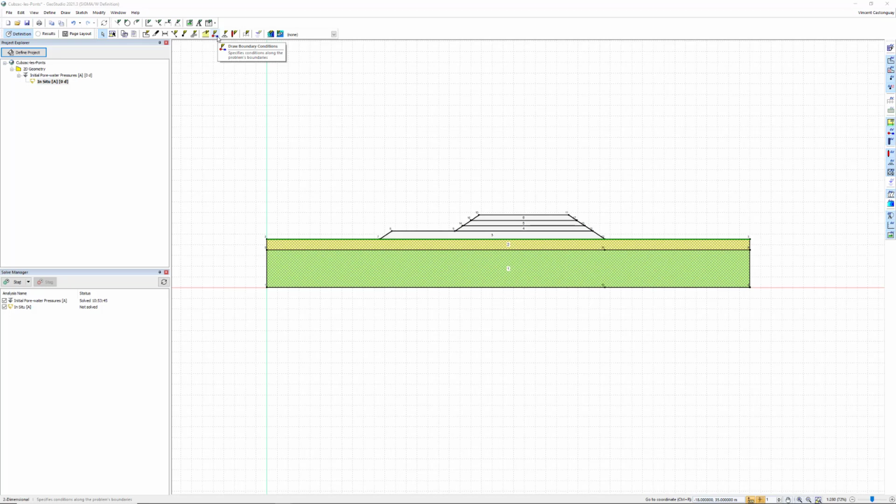More specifically, we want to prevent displacements of the nodes located at the edge of the geometry so that they do not sway sideways once gravity is applied, or when the embankment is constructed. Similarly, we want to prevent displacements of the nodes located at the bottom of the geometry so that gravity has something to push on when it is activated. Otherwise, when we turn on gravity, the entire geometry would slide downward toward the bottom of the screen.